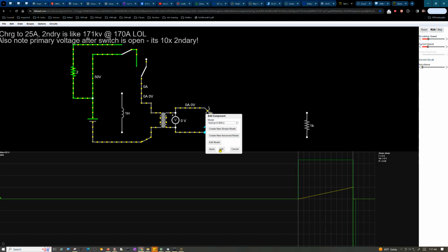Because it's not going to do you any good to drive the core into saturation, and I'm not really sure how much current it takes. Like I said, you think, well, geez, if it's a 10 amp secondary transformer, it may take that 1 amp on the primary. But again, with DC, that may not be the case, because remember, the voltage is constantly changing. So just be cautious when you're doing that, because otherwise you might get bogus results at the very least.